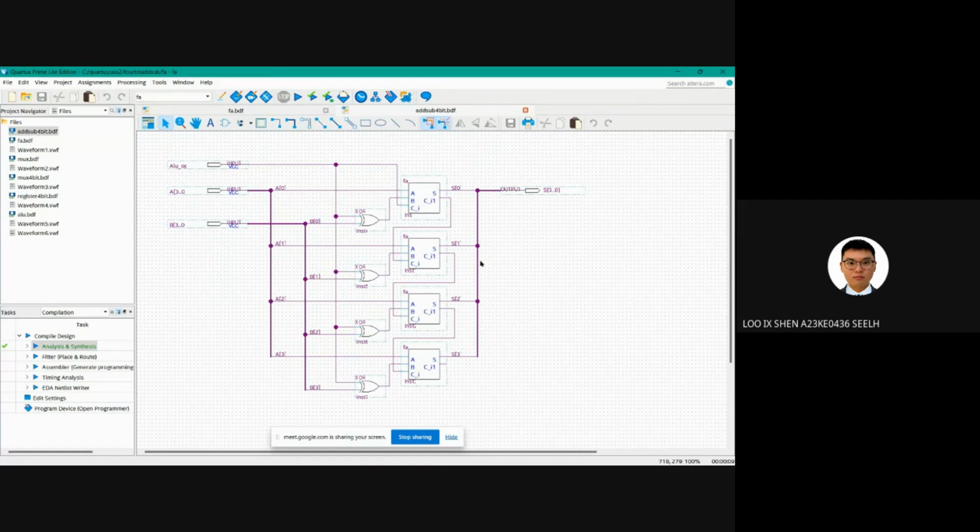So this is a 4-bit adder and subtractor. This circuit consists of 4 full adders, for which I created a symbol for each full adder. Since operation of 4-bit numbers is performed, A and B represent the 4-bit input values, with MSB to LSB indexed from 3 to 0, while the ALU option to add or subtract the numbers is connected to the XOR gate.